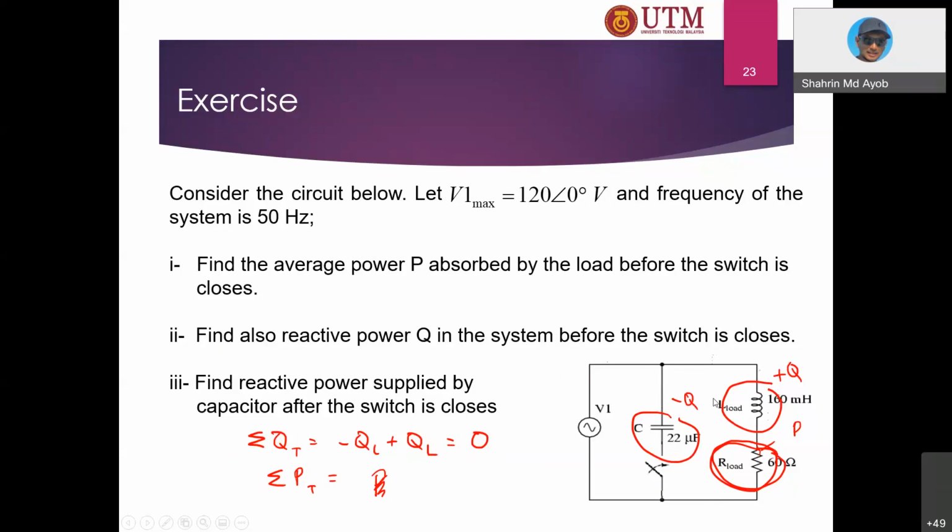But it is actually the power factor correction. If you go to Giant, Tesco and so on, I think lately they are no longer there, but in previous years, when you went with your family, sometimes people approached you to reduce the bills and so on. They introduced some black box. By installing that box, it will reduce the bills. What the black box does is actually just a capacitor.